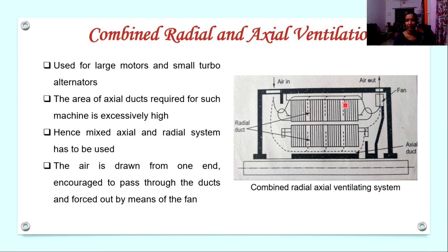These are the radial ducts. And air will enter into the machine. It will flow through the axial ducts, radial ducts as well as through the air gap, and then it is pushed out to the atmosphere by the fan.